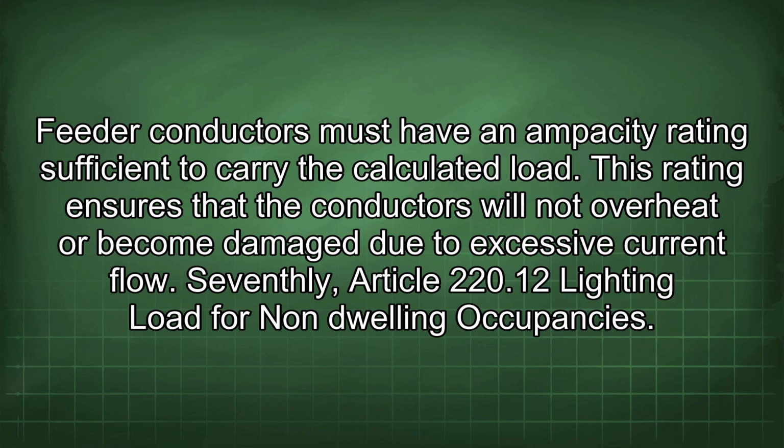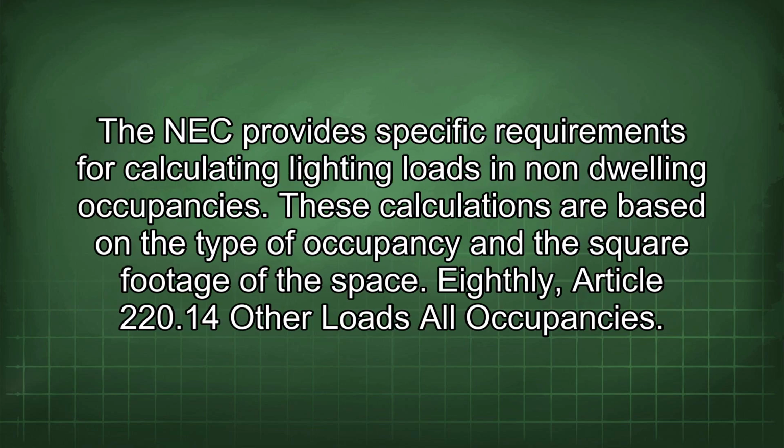Seventhly, Article 220.12 Lighting load for non-dwelling occupancies. The NEC provides specific requirements for calculating lighting loads in non-dwelling occupancies. These calculations are based on the type of occupancy and the square footage of the space.